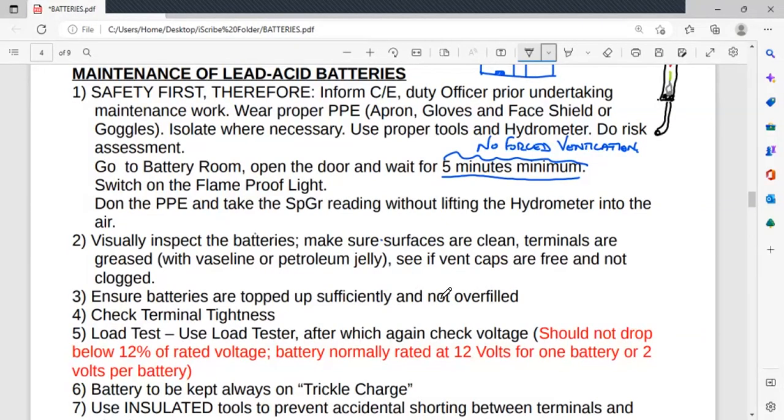And yes, people say you can use this, use that, save the company's money. But what are you doing? You're damaging your batteries earlier than normal. Normally you are supposed to change your lead acid batteries in 2 to 3 years. Instead, maybe within a year that battery is gone. Blame it on putting normal water. You're supposed to be putting distilled water.